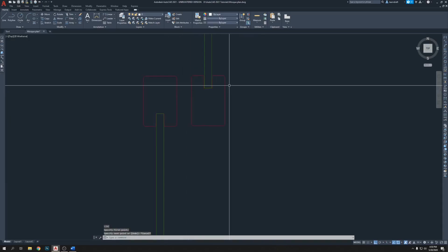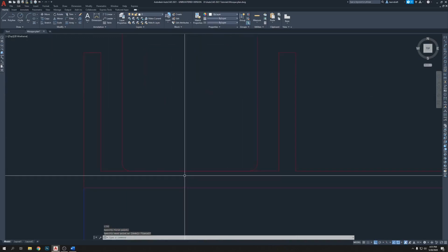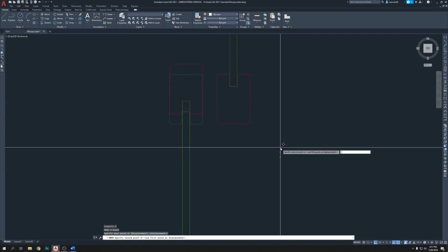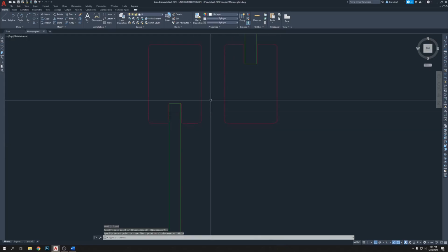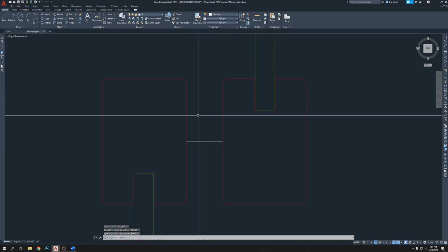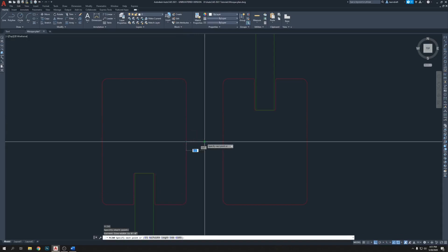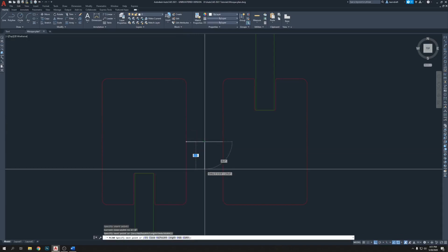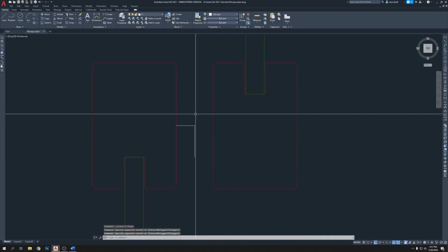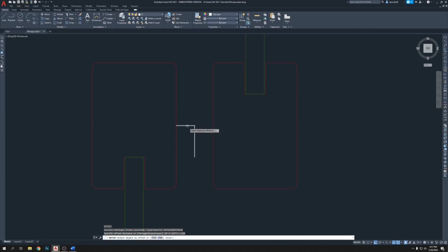Okay, it's not actually straight because of this one in the end. So I'm going to push it for move 0.03125, which is 1/16 of inch. Now it is a line. So draw a line here, and then PL, enter, select, click the center, come this way like 0.75, which is 3/4 of inch. Take out this line and then offset this one 0.125, which is 1/8 of inch.